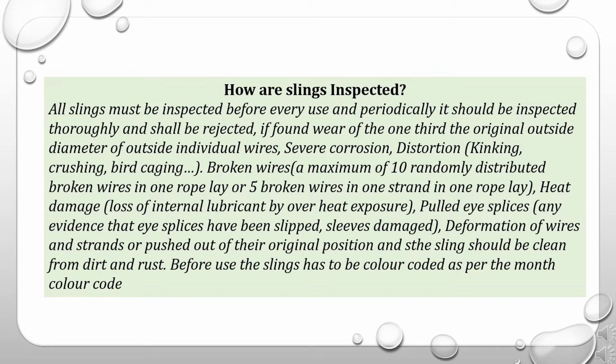Heat damage, loss of internal lubricant by overheat exposure, pulled eye splices, any evidence that eye splices have been slipped, sleeves damaged, deformation of wires and strands or pushed out of their original position. The sling should be clean from dirt and rust. Before use, the slings have to be color coded as per the month color code.